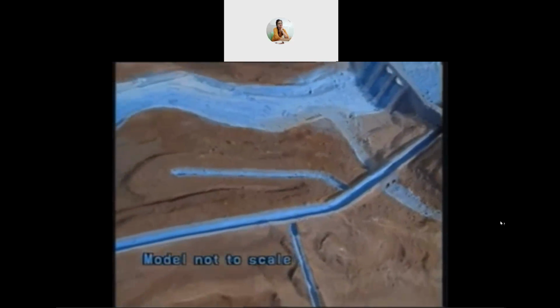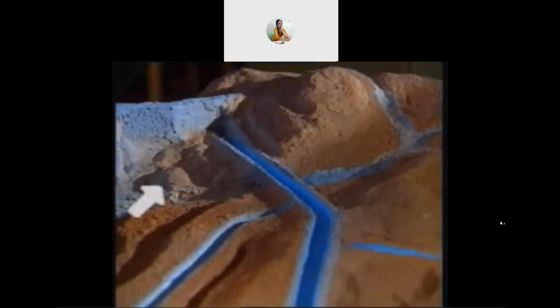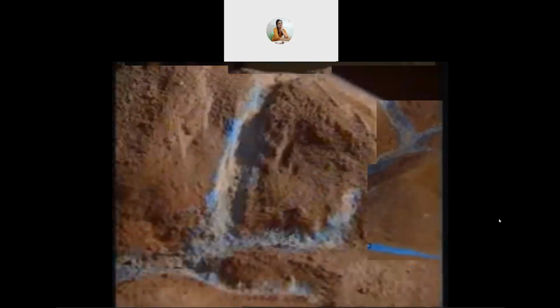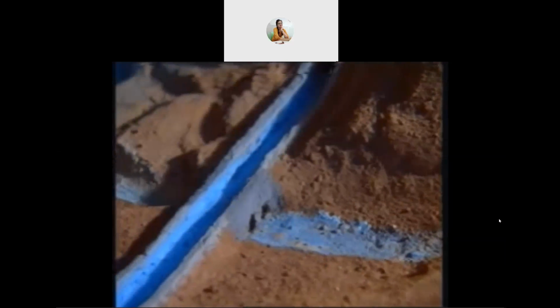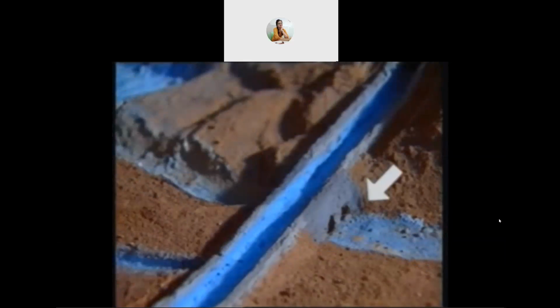Irrigation channels are generally aligned with reference to contours. A channel aligned nearly parallel to the contours of the country is called a contour channel. As some contours are higher on one side of the channel, a contour channel irrigates only the other side of the country. While laying a canal system, we may encounter natural drainage, such as a river, which crosses the canal at right angles. When the drainage bed level is lower than the canal bed level, we construct an aqueduct to carry canal water.